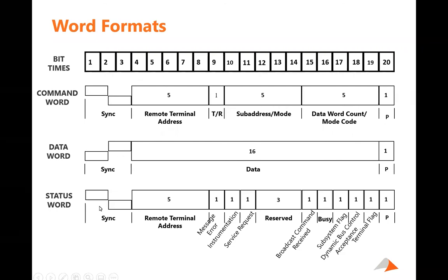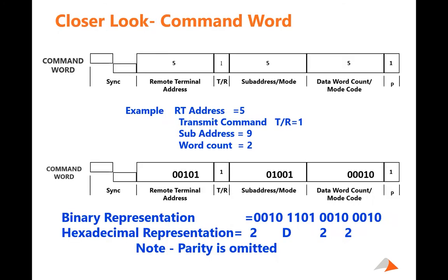If the RT is to transmit data, then the status word goes out, and right after it is the beginning of the data words, and they'll be contiguous. And so that's how you know which message interaction the data word belongs to. All right, Roger. Thank you. Okay, and we'll see that here in a layout that I've got in just a little bit.